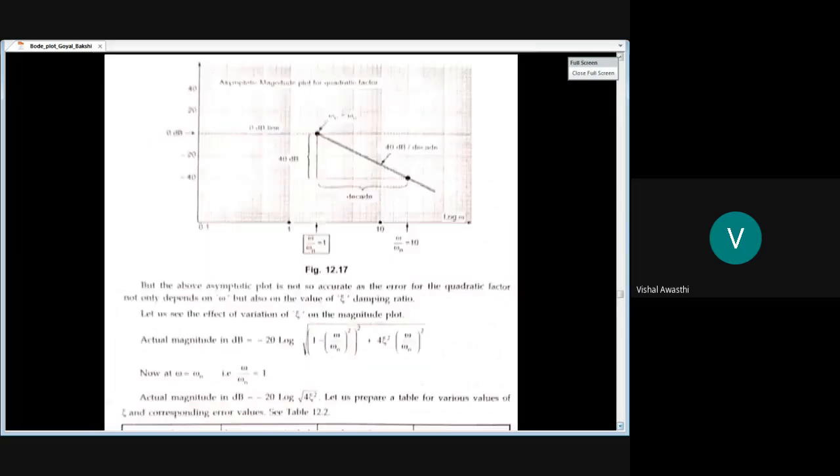And when you have to do that in your Bode plot, just convert this into your time constant form and divide this frequency into low frequency and high frequency range, and then find out its corner frequency with respect to that simple method, and divide this plot into high frequency and low frequency.